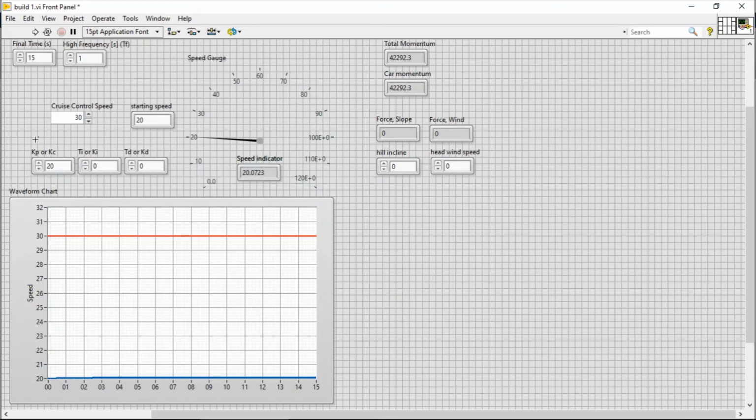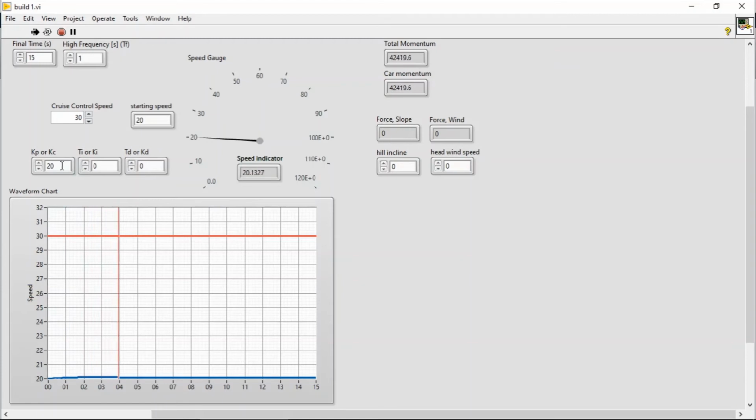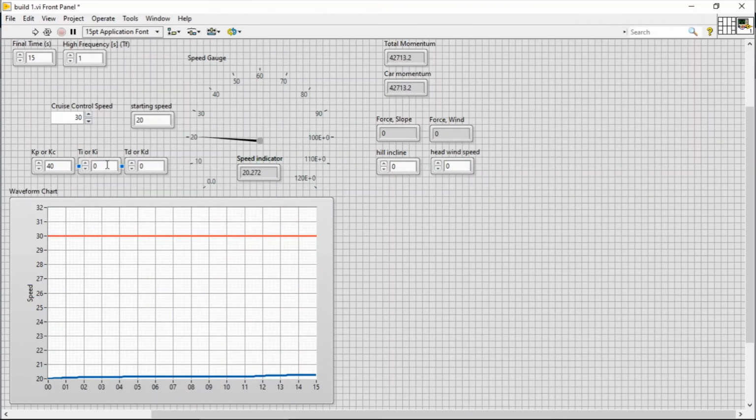And so basically what I did was a lot of fine tuning, taking values and doubling them until I saw something I kind of liked, and then doubling them again until I found something I kind of liked. And then I started in with the integral time frequency and decided that messing with just these two right here, KC and TI, you don't need to worry about the KI or the KP in this one. I put those so that it was noticeable no matter which of the 3 different types of controllers I wanted to use.